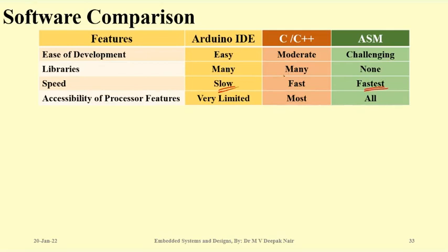So nowadays, a combination of these two is used to design good driver files. That means some part of the program will be C, and whenever you need very typical activities to be done in a very small time period, you will go for assembly. Mix those two and make a good program. So these two are nowadays integrated together. But apart from that, assembly is the fastest.